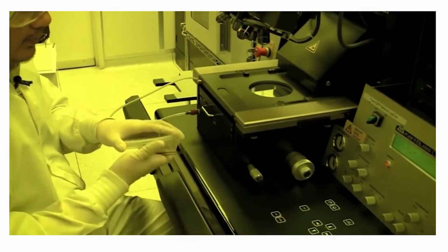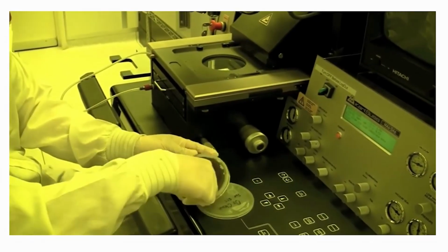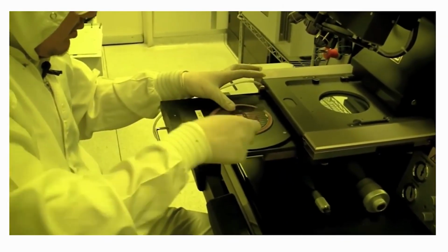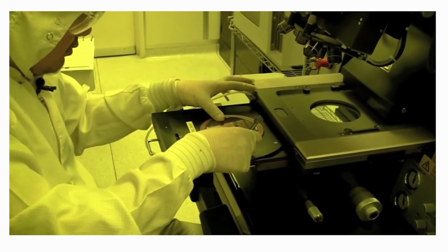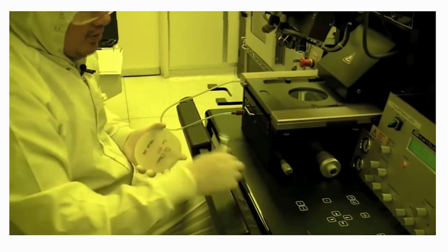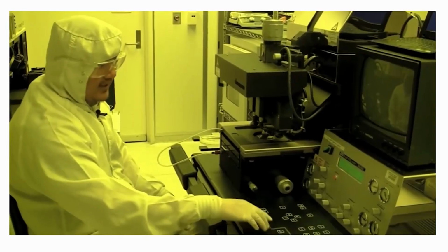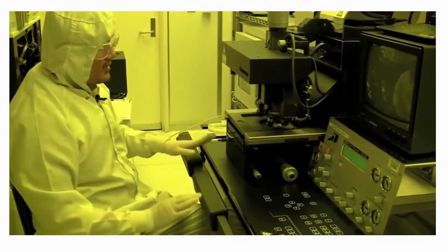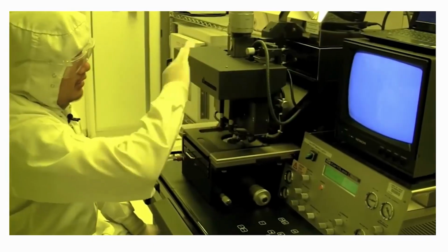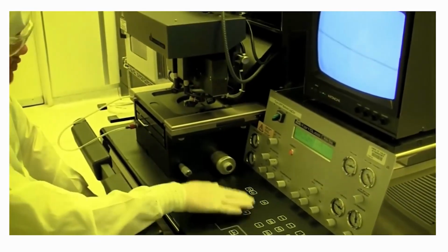So again, you press load, and it says pull slide and load substrate onto chuck. And then you press enter when you did that. And the microscope will automatically come down because we have the BSA microscope light button off. So now it's down, we turn the TV screen on. And what this is doing is putting the image from here onto the screen. So again, these buttons right here control the X and Y position of the microscope.